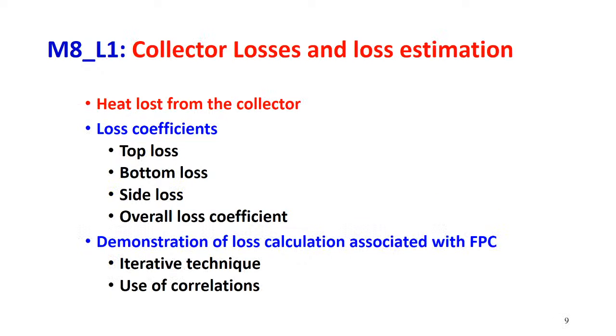In module 8, lecture 1, we have studied the collector losses and loss estimation. What are the different losses involved in the collectors, which has to be studied clearly, otherwise we cannot estimate the kind of losses taking place and our design will not be perfect. These loss coefficients involve top loss, bottom loss, and side loss, and if we combine all three losses, we get the overall loss coefficient.